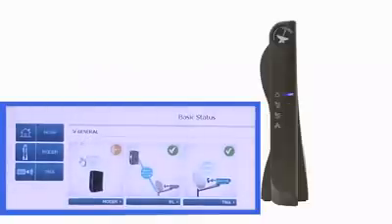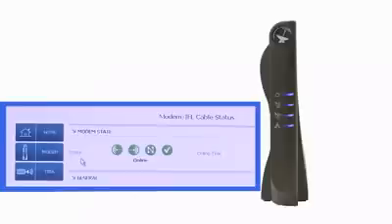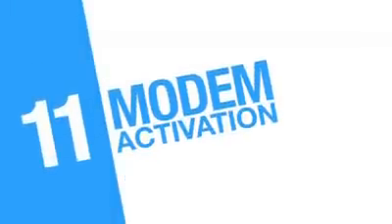The first stage is receive synchronization with the network. The modem then ranges and synchronizes its transmission and enters the network. It then receives DHCP and network information. Finally, when the LAN LED is blinking, it's on the last stage of synchronization. When all four LEDs are on, the modem is online. It is ready for activation with the activation code.